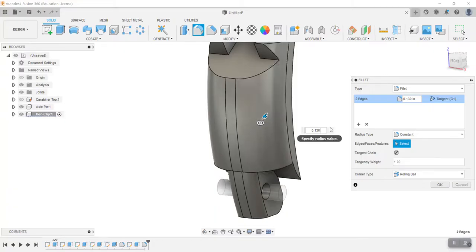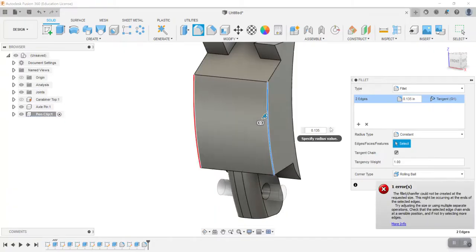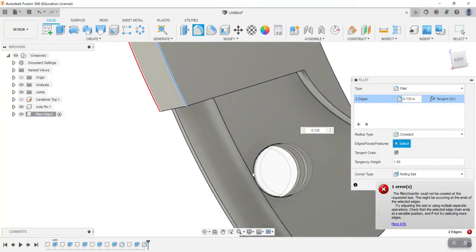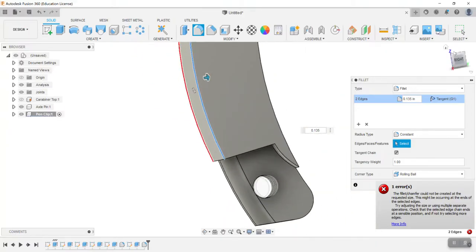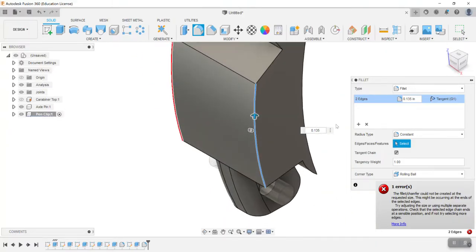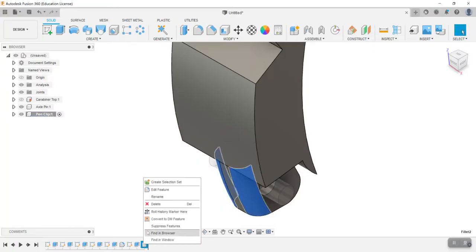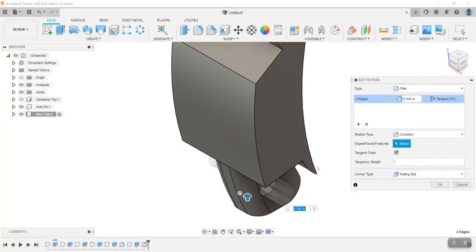To me, you could start to see, as you try to match up those particular cases, that you could go through and round some of those off. The issue you've got to watch for is to make sure that this radius doesn't interfere with the hole down on the bottom. We're just going to see how these two fillets respond to each other. So 0.04 is probably a little bit too much.